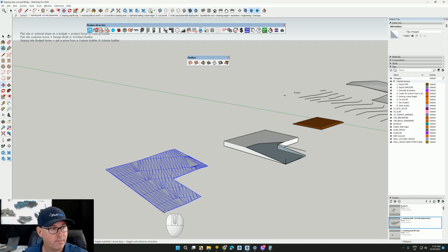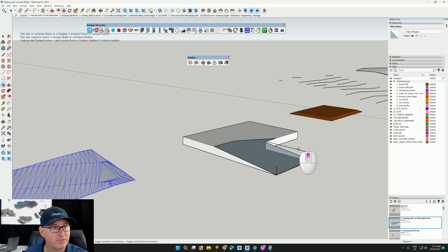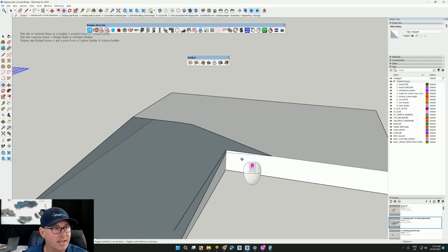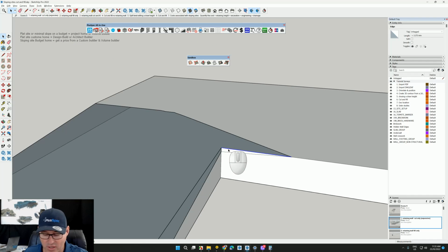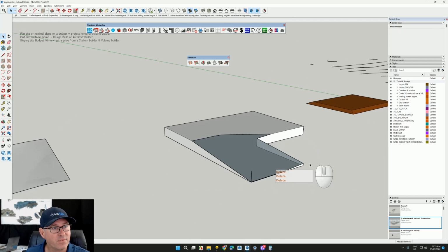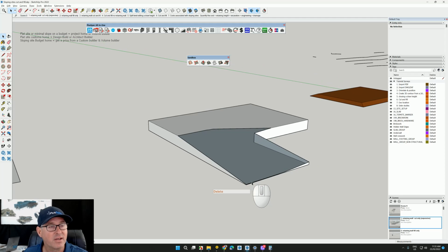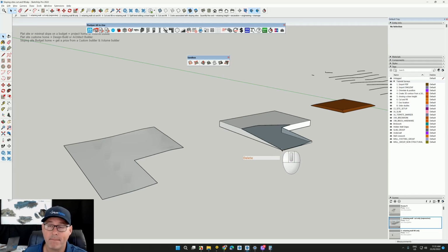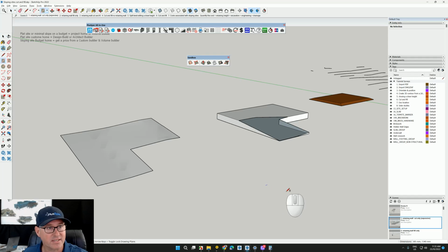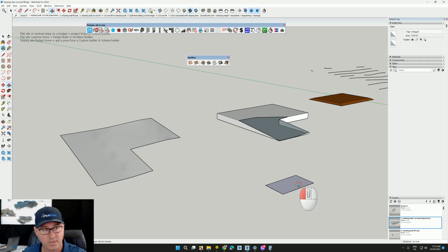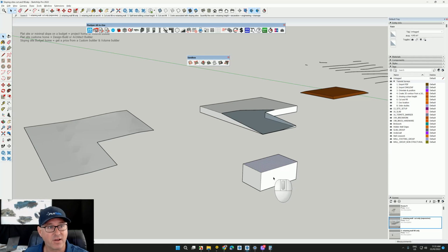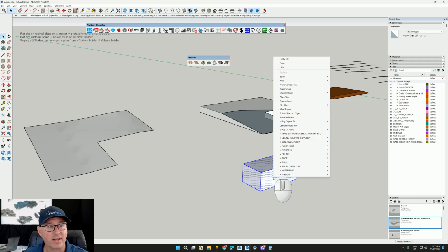Move. Now one thing I do need to be very careful about before I do that is I actually need to ensure that I don't have any straggly lines around, because essentially to create a cubic measure we have to have a manifold is the word. It means it's watertight, and I'll quickly explain that. Rectangle, push pull, I'm not sure what size it is, but if I actually triple click that, right click and make it a group,